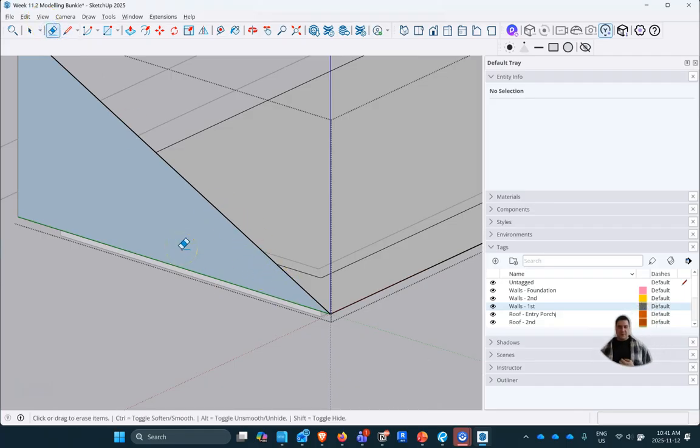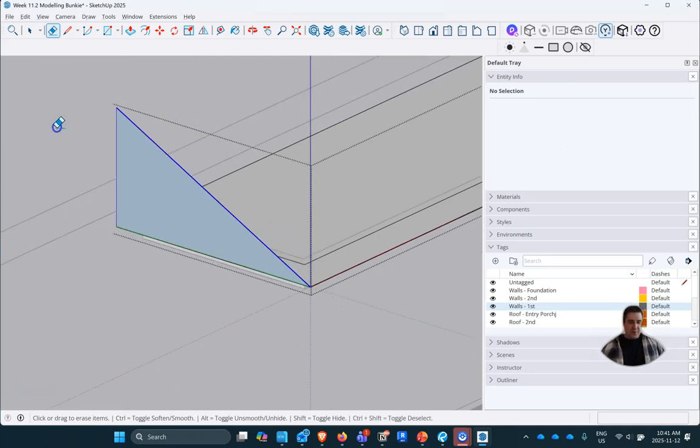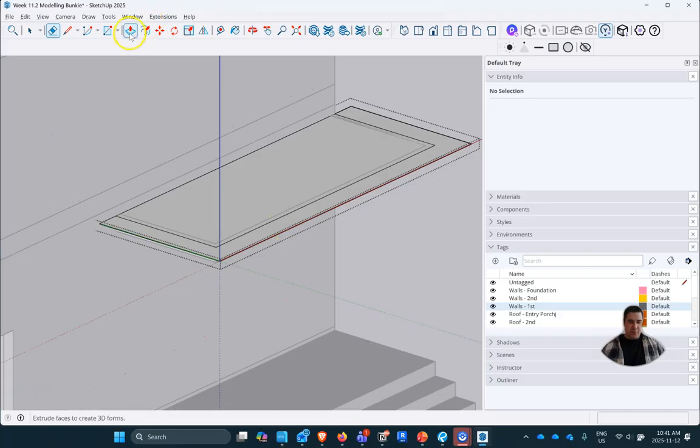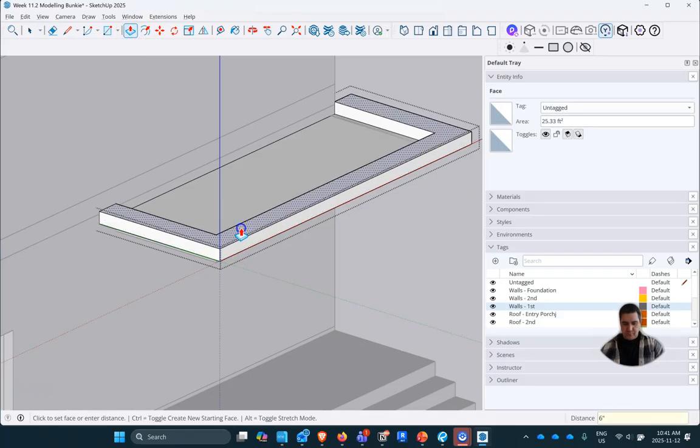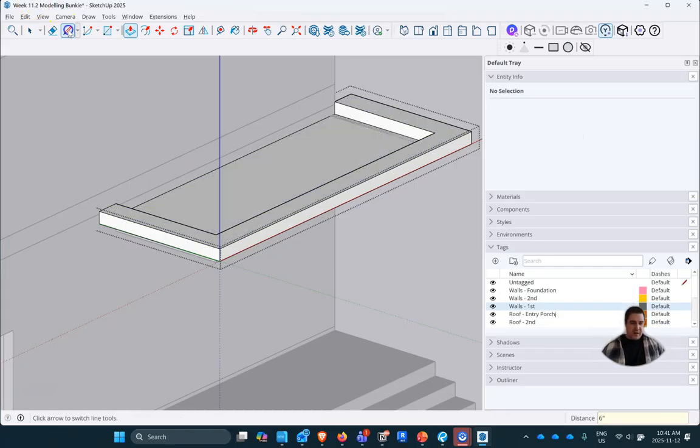So let's clear that line off there. And actually, one thing I did not do is a fascia board. So let's do a fascia board. Let's extrude this up 6 inches. And then let's do that slope line again. So let's go over 12. I went over 12 feet. I'm not going to do that. Let's go over 12 inches. And let's go up our 6 inches again.